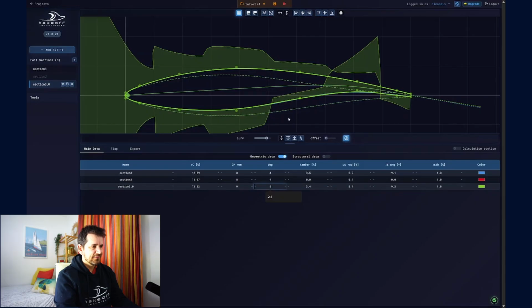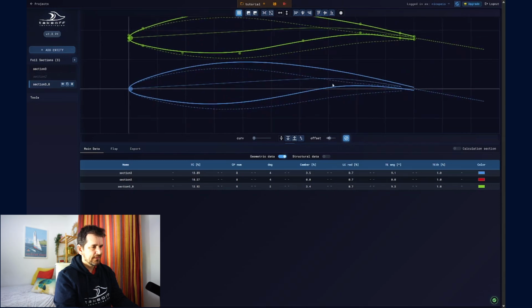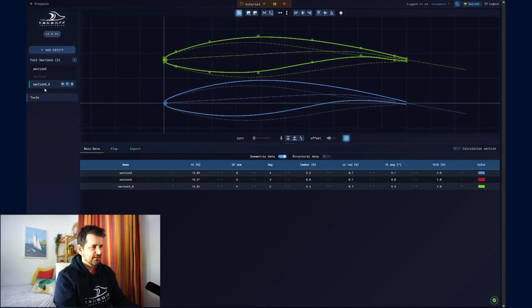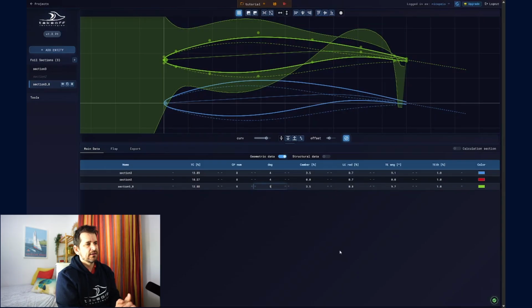And if you look by eye, the section looks exactly the same as the blue one, but in reality you see that the curvatures are really kinky, which can give you some issues in real life. That's why the curvature plot is really important and really helpful. Normally we use between degree 4 or degree 5. It ensures you have smooth geometries of the sections.